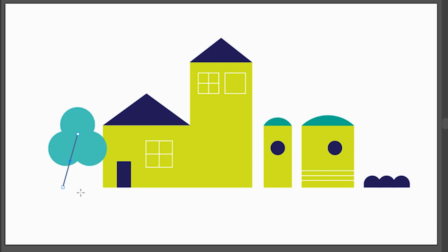To edit the direction and length of this line, move the pointer over the bottom end of the line. Click and drag, and you'll see that you can move one of the points. As you drag, press the Shift key, and the line will be constrained to 45 degrees. When it's straight up and down, release the mouse button, and then the key.